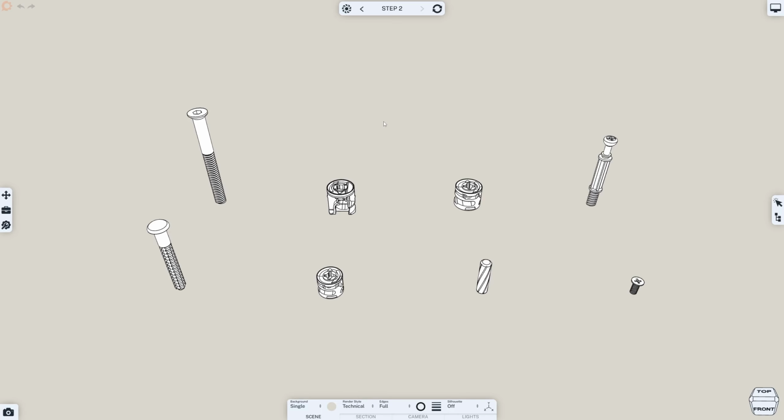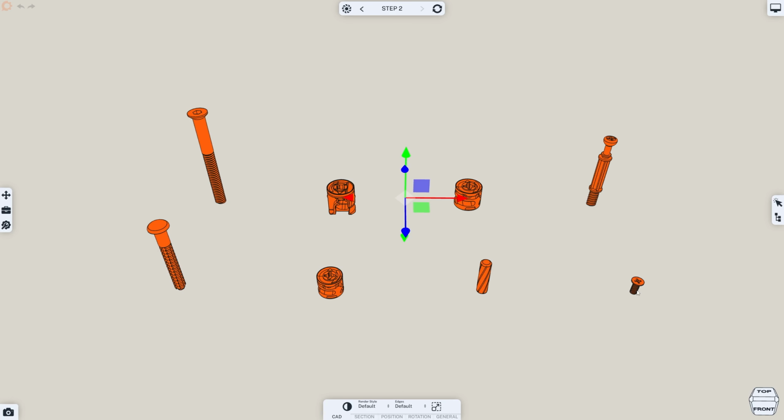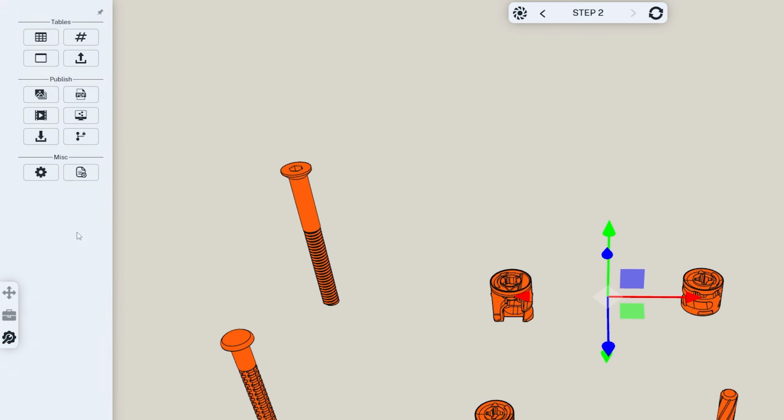These types of views often include callouts with item numbers. In Cadasio, item numbers are just a property of the part, which you can manually change in the meta properties. This works well if you have specific values you need to use, but often you may just want to number the visible parts in order. This can be quickly achieved by selecting the objects in the required number order and choosing the Item Numbering option from the Tools tab on the left-hand panel.